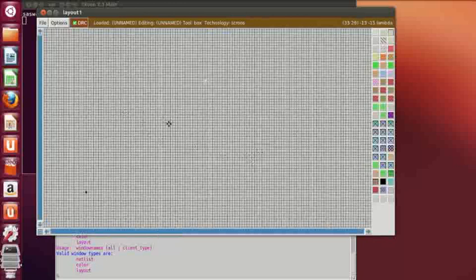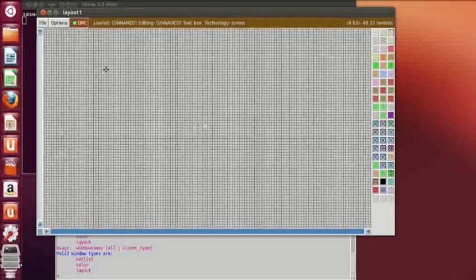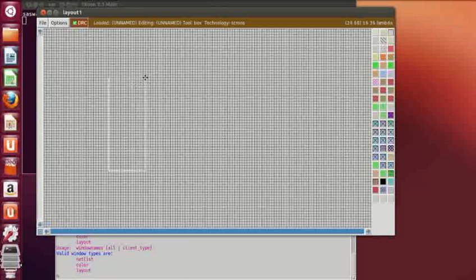Now when we are trying to draw the layout from the untwisted schematic, we have to place the NMOS and PMOS as they were in the untwisted form. So if I select this area, then we have to select the n-well. This is the n-well. So we have to middle click in the mouse.